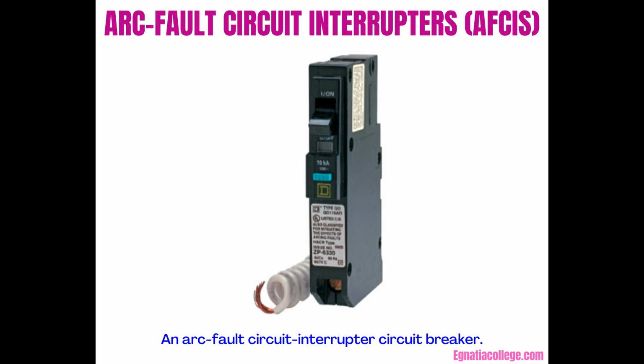When the iron draws current, arcing will occur at the point of the conductor break. The current drawn by the iron will not trip the circuit breaker or fuse protecting the circuit but can develop intense heat at the break in the wire. Arcing faults can result from such things as poor terminations during installation, equipment failure, and the failure of conductor insulation due to circuit overloading or improperly sized overcurrent protection.